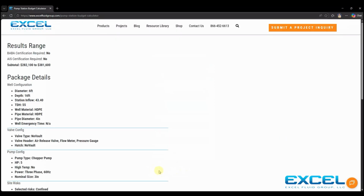So this is the result of the budget calculator. So Build America, Buy America certification and AIS is not included. And then the pump station, we've got an HDPE 6-foot diameter by 16-foot deep wet well. We've got our design inflow, and then the TDH details, our pipe diameter, that would be for your piping and valves and the force main. We did not select any additional emergency storage requirements in the wet well.